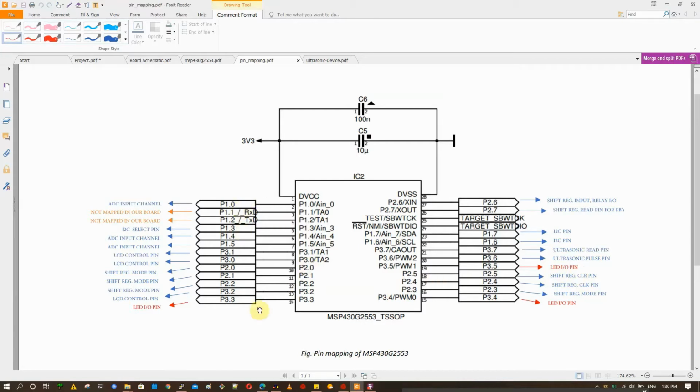After implementing everything, we had only 3 pins left for use. So we interfaced them to the 3 LEDs, which we will need for the fourth question. We measured only PB1 to PB4 and used the remaining 3 pins for our 3 LEDs, red, green and blue respectively. A copy of this document will also be placed in the project folder for reference.